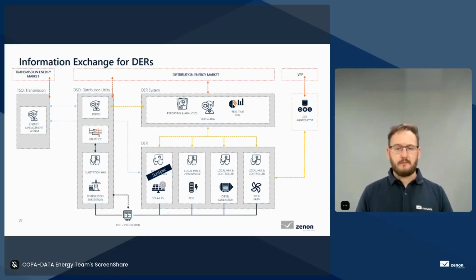Now, SunSpec base data models on Modbus TCP, and it's extremely widely used and embedded into inverters from most of the big names in manufacturing, and also for weather systems, smart loggers, things of this nature.